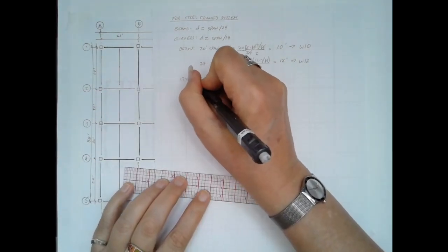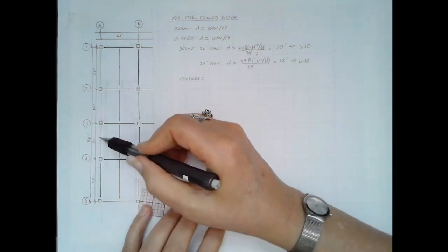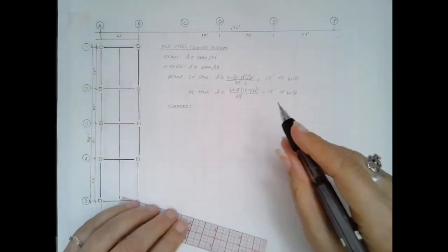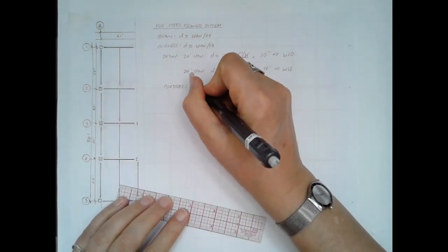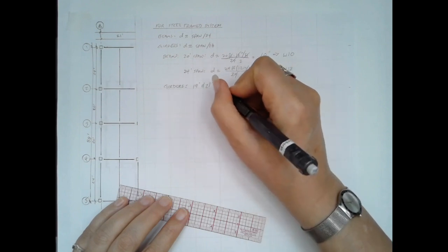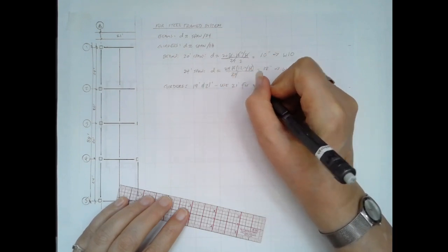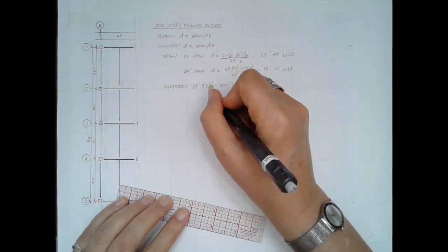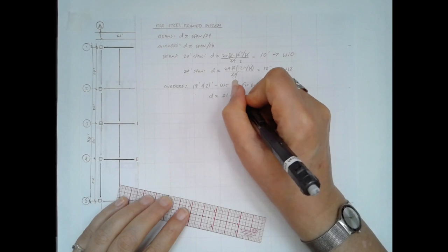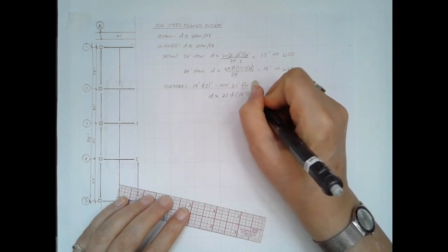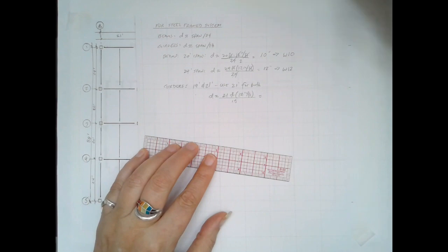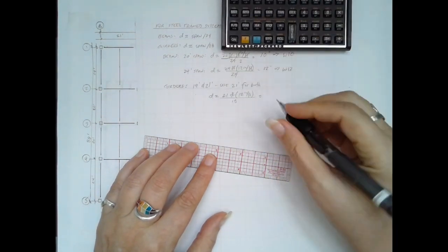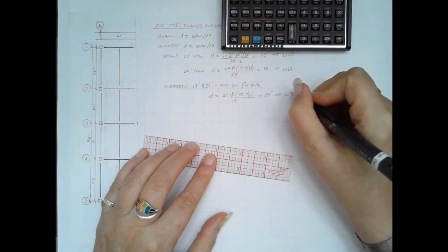And then we go on to the girders. We have several girder spans. 19 and 21 are close enough. We'll just use the 21-foot span for that to account for both the 19 and 21. So 21 foot for both. So the approximate depth there, again, span over 18. 21 times 12 over 18 is 14. So that'd be a W14.